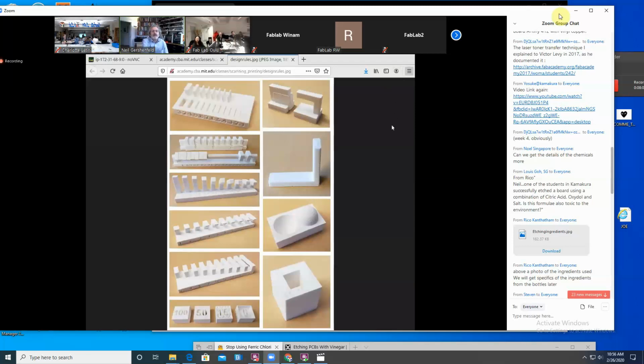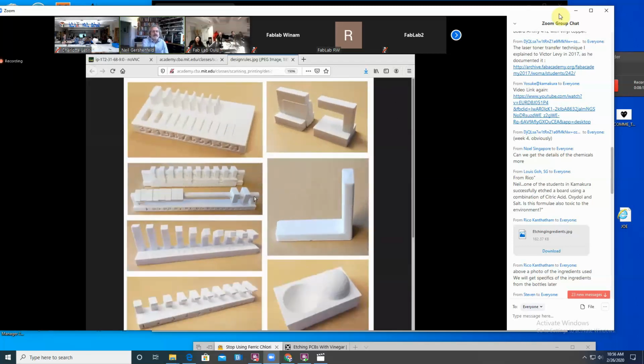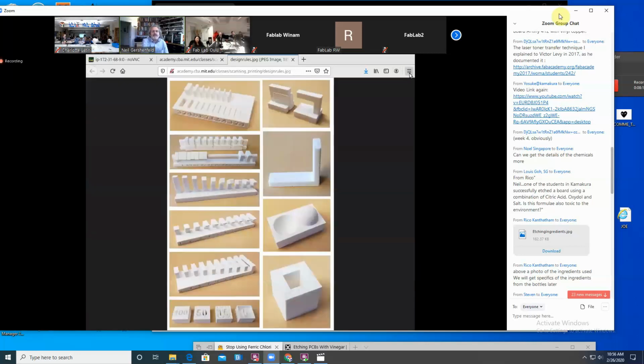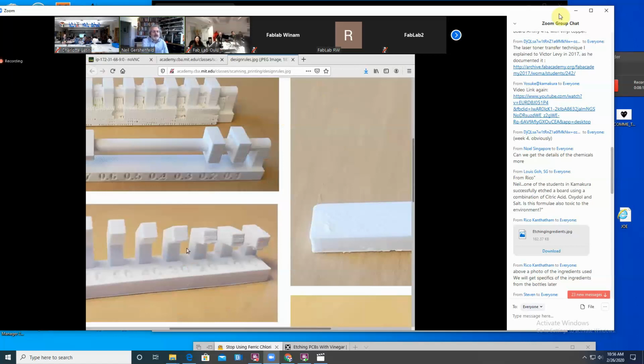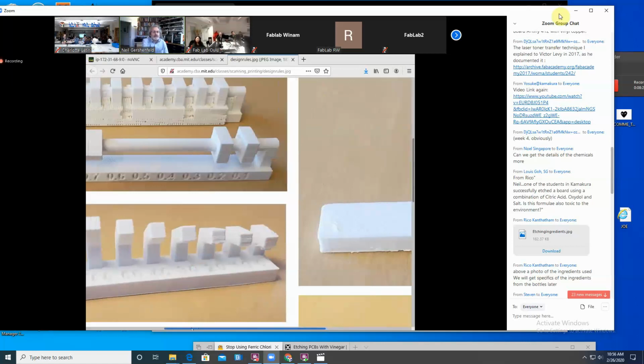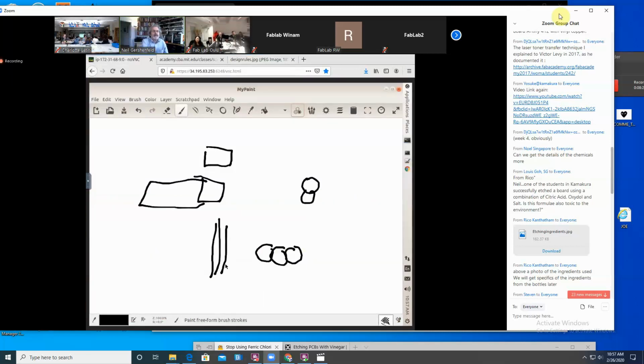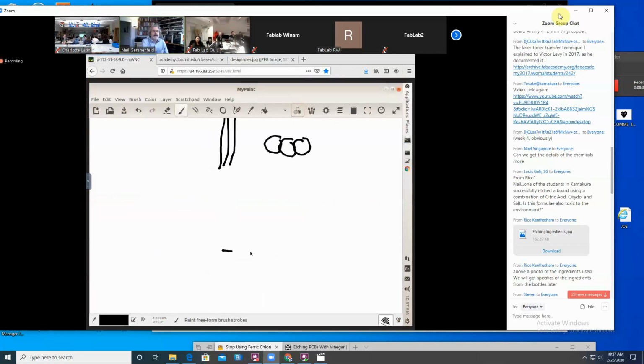This next one is the angle. And so what this one is doing is when you build vertically, you just build vertically. As you start building horizontally, when you start making paths, there's an angle where each one can overhang the one before it.